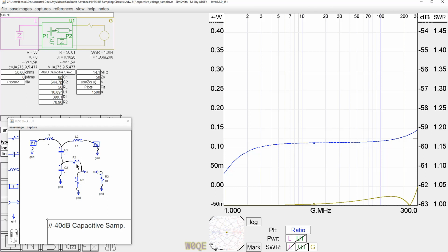We ended up having to attenuate the signal a lot more, and that may not be acceptable. Personally, I don't like this scheme very much, but this could work. In the past, I've done this many times where I just take two capacitors to couple a signal to some kind of spectrum analyzer or something like that. But I'm generally not looking at harmonics. This would allow me to look at harmonics and I can correct for it a little bit if I needed to, but it's not much of a correction. So you might say this is tolerable. I don't really like it that well.